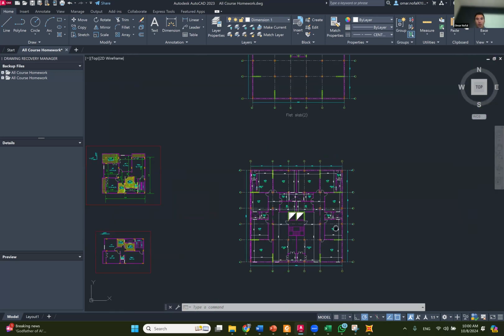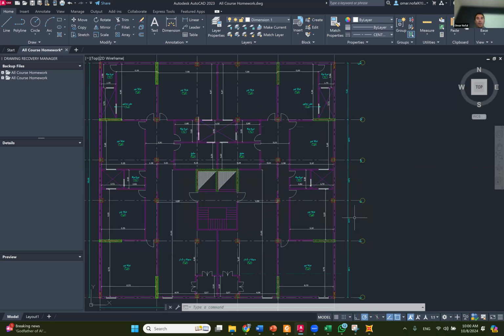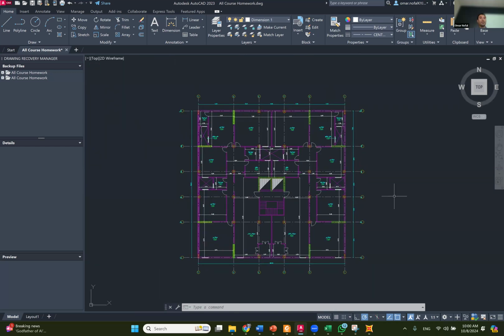All right, so this is how the whole process starts. You are a structural engineer, and there's an architect who had a building like this designed. I'm not sure if it's an office, but actually this is one of the buildings that I have in Egypt. I can see they are all residential buildings. There's an elevator here, a double elevator, and there's a staircase here. So basically, we have a flat slab. You can do a solid slab, whatever you decide, depending on the span of the system that you have, but we are going to do it as a flat slab system.